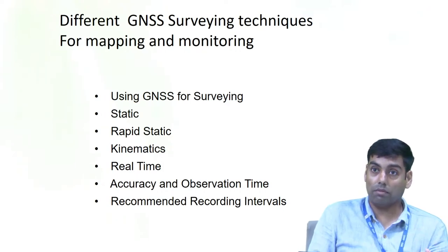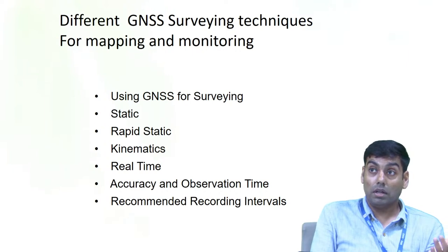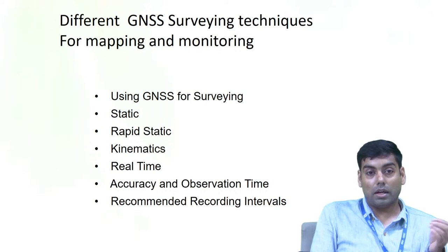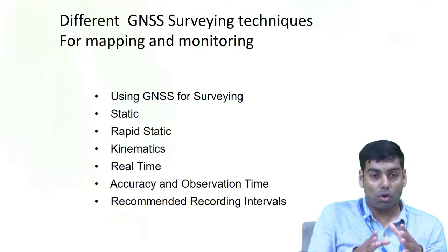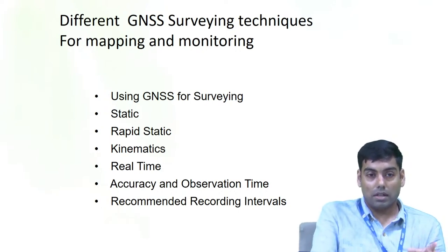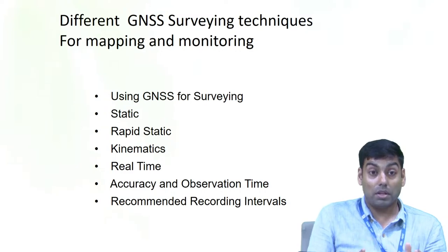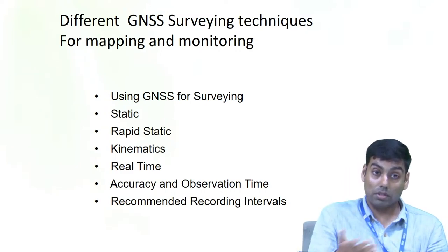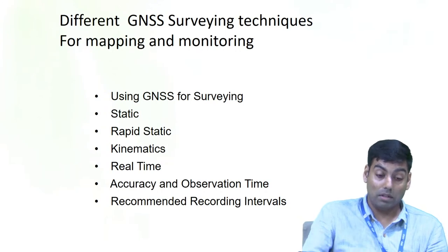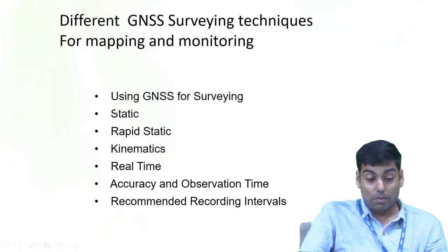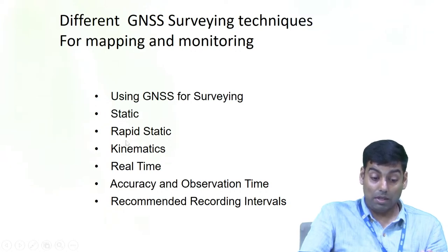Like when we are planning landslide monitoring, land subsidence monitoring, dam monitoring, active tectonics, fault monitoring, crustal deformations, all of these require a static setup of GNSS antenna and receiver, and it should be very robust. So it comes under static measurement. Then GCP is also part of that. Some GCPs are static and some GCPs are rapid static or kinematic also.